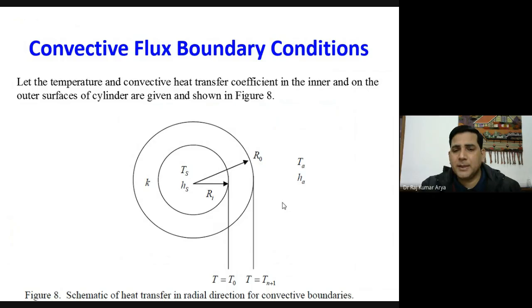So that's one way. How can you control that? You can again put an insulation layer on it. Another way is to change the outside surrounding atmosphere, but generally that's not possible. So maybe you can put an outer cylinder with a gas which has a very low heat transfer coefficient, and fill the gas inside the cylinder. That could also be possible.